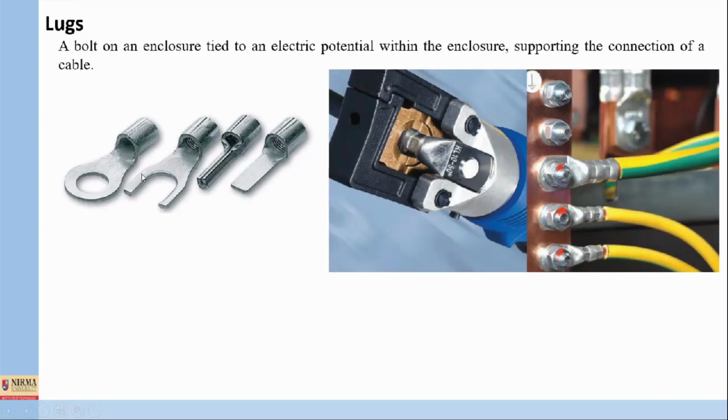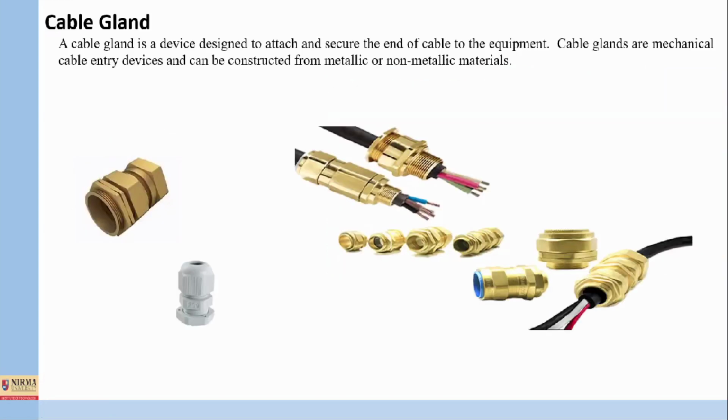These are the cable lugs. Cable lugs will be fixed to the cable. Now this will be fixed by bolt so that it will be a firm connection. There will be no loose connection, no sparking, no carbonation.